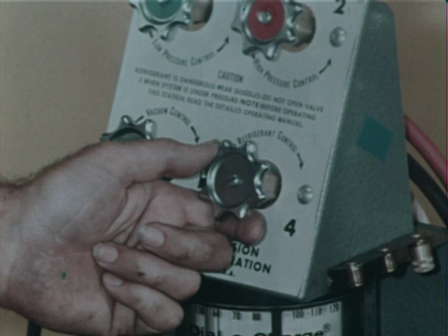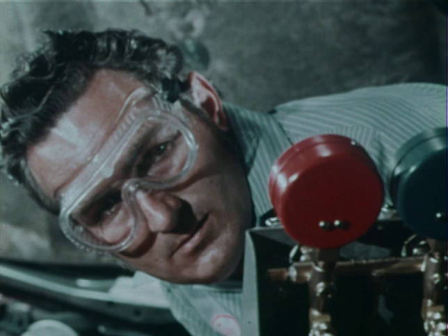Start the engine and engage the compressor in order to draw refrigerant into the system. Open the refrigerant control valve and allow refrigerant to enter the system. As we have noted, the refrigerant should be added 4 ounces at a time after performing the refrigerant quick check test. Remember, though, that a restriction in the system, as well as a low refrigerant charge, can cause the evaporator inlet pipe to be cooler than the outlet pipe.